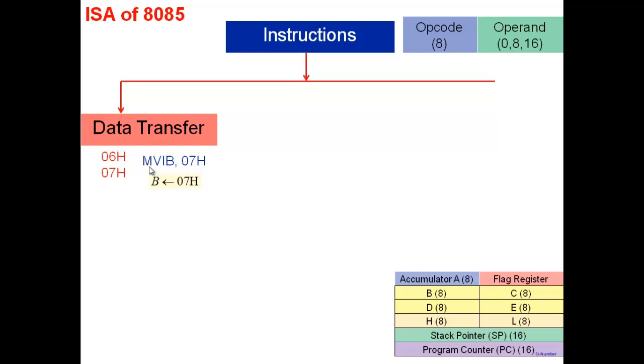So this is written in mnemonics, MVI B, 07H. Okay, so there's an instruction like this here. What does the first one denote? In the actual memory, it would be stored like this: 06, and then in the next place in the memory, 07. So the memory has a 06 stored in it and a 07 stored in it. And that's the complete instruction.